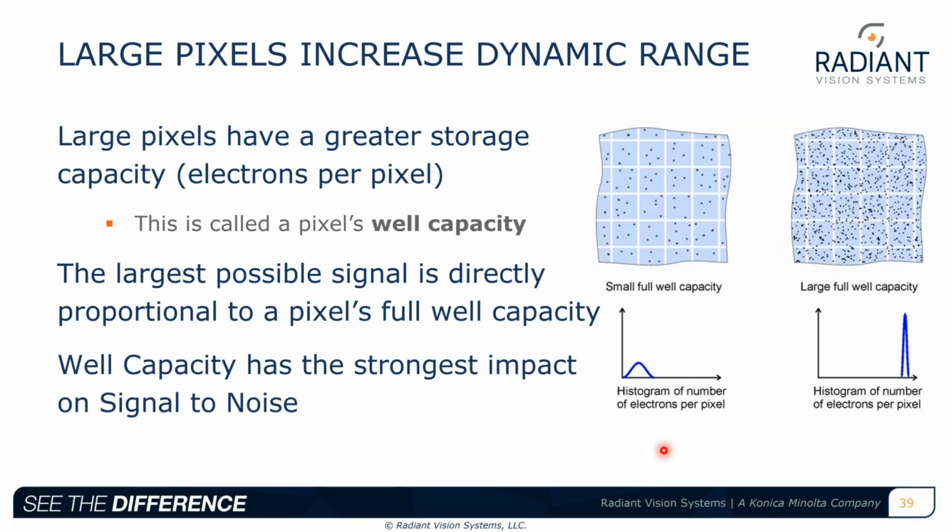One way to reduce that is to cool the CCD. You can also do dark frame subtraction. Basically, you block your optical path so no light is getting in, but you're still measuring some light, and you go through and subtract that pixel by pixel. So that was noise. Once we've done everything we can to get rid of noise, the next thing we can do is boost signal.